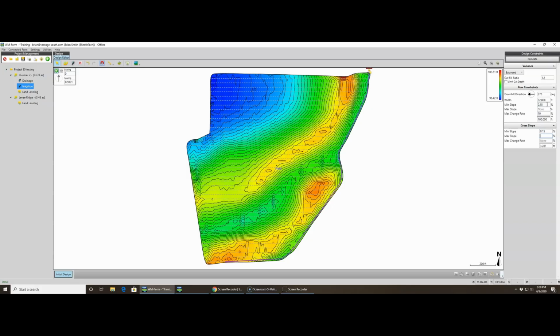First off, what I like to do is leave this on nothing. I come down here to 10 again and then 300. So what this is doing is just smoothing the side to side contours. Now you see how I had a 0 in here. That would not let it fall. That would basically straight levee this field, like the contour lines would be straight. So you want to just leave it on none if you just want to smooth the contours.